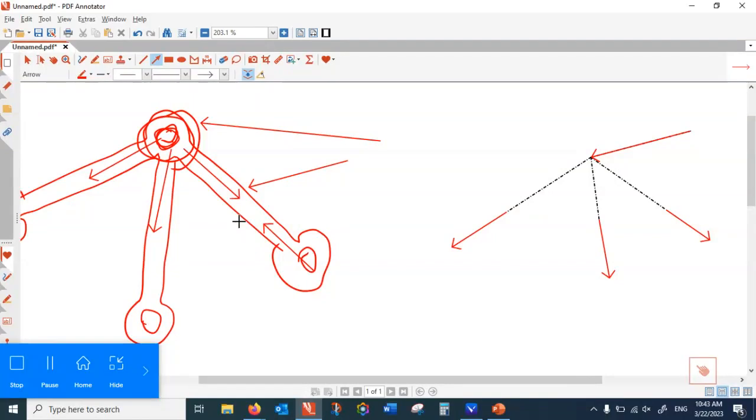So you have to have a strategy. Okay, I deal with this node first, that node second, this node third. If you change the order, the problem is not solvable, because you are attempting something which is not solvable. Three unknowns, four unknowns, two conditions, that's not solvable. So you have to choose how to start.